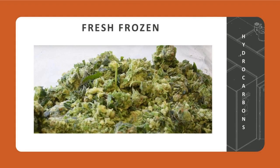And so a lot of folks that extract with fresh frozen product will fill up the column in their closed loop system with their frozen plant matter. Then they'll chill that column in a sub-zero chiller, something you might use for winterization, for example. They'll get it nice and cold, or have a jacketed column attached to a chiller that will keep the column cold as you process the solvents through it.